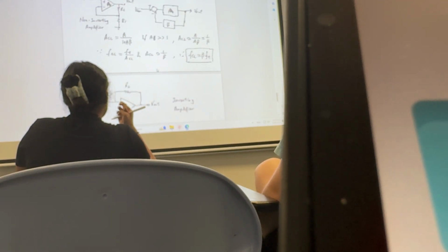This one corresponds to here, right? And this one, you have V out over V in, the R2 ratio, after you solve it, right? So both can give you the block, the signal flow, for the control. This is a control concept. Okay, this is a control block diagram. This is your op-amp diagram. So you can prove from op-amp theory, or you can see from control theory, it also gives the same identical transfer function for closed loop gain.